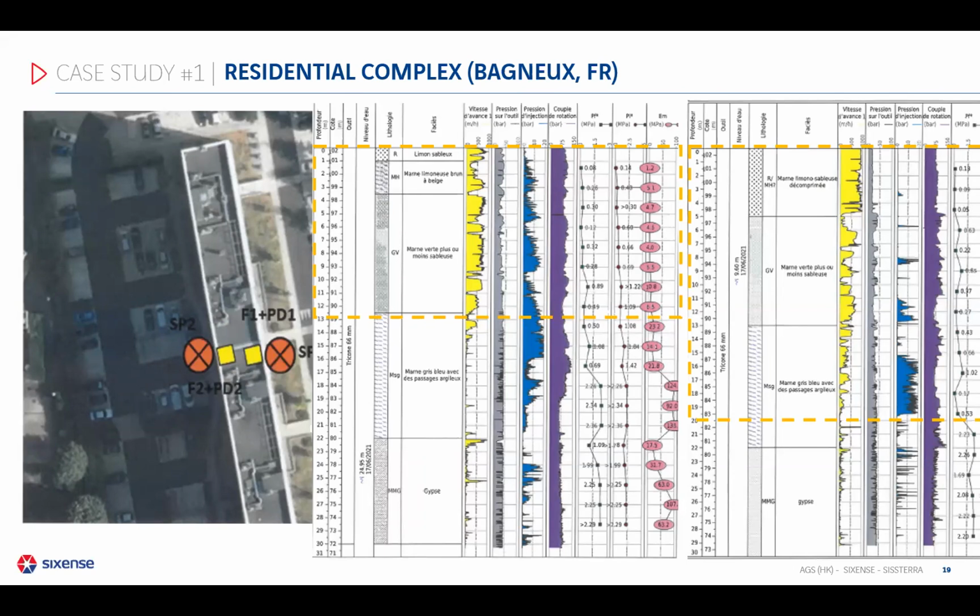except that when we look in detail at the drilling parameters, it appears that the drilling speed, indicated in yellow here, is varying a lot within the geological layers. That means even though the geological layers are quite regular, there is a different weathering state of the materials in the marl layers, and the very top of the marl layers, the 6 to 7 meters at the top, are softer, or at least they present some low geotechnical characteristics. It suggests that weathering state can vary laterally below the building, and maybe explaining the differential settlements.